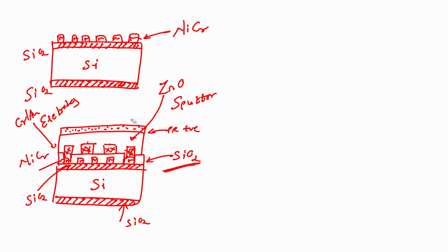If I develop the wafer, then I will have my photoresist only in this area, because I used a bright field mask with a positive photoresist, and that is why the unexposed region became stronger. After this I will go for hard bake, 120, 1 minute.